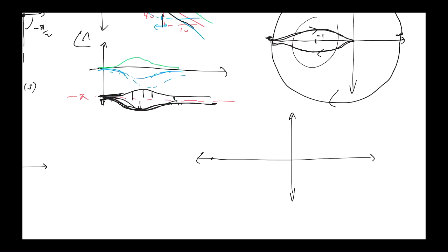But because the lead compensator now pushes the phase this way instead of this way, right? It goes like this, right? Whereas with the lag compensator, it went like this. It went into this quadrant. Now, the lead compensator pushing the phase like this pushes you into this quadrant, right?